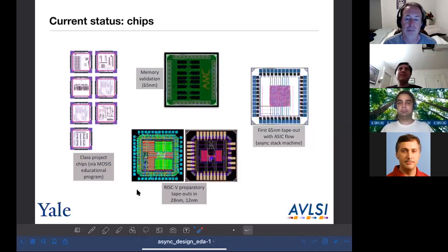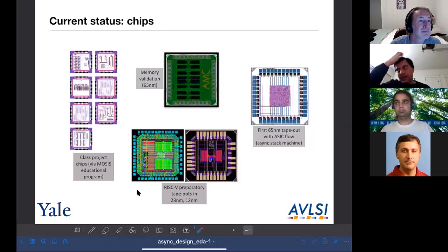And I didn't talk about this, but we actually have a standard cell generator, which kind of works. I won't say it works. It does the placement of the transistors for you. It draws all the diffusion. It does all the stuff except, and it partially does the routing of the wires. And then you have to finish the cell manually. We finish quite a few of the cells, but some of the cells you have to finish manually.